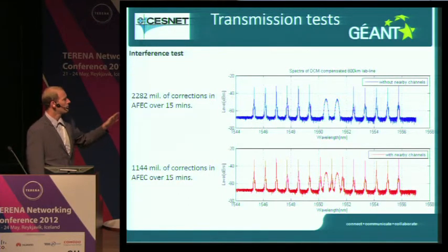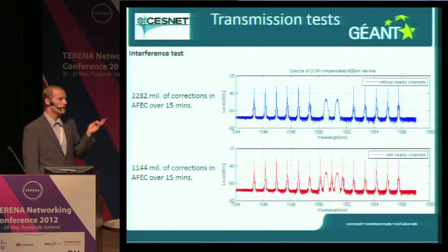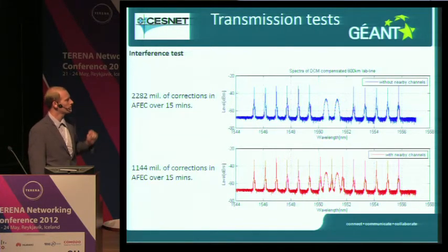We set there 14 lambda channels, 10G each of them, and then we slipped in the 50 gigahertz. Those 10G lambdas are on 100 gigahertz spacing, and those 2 100G channels are on a 50 gigahertz spacing, slipped between those 10G.